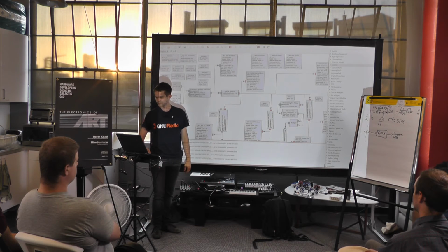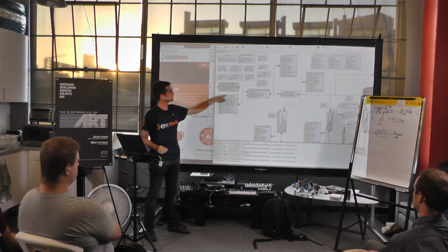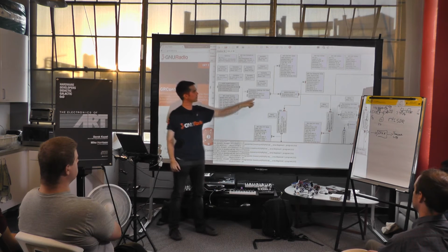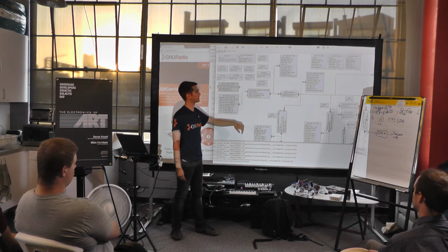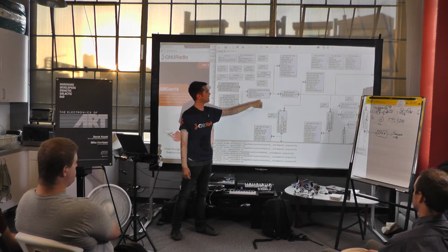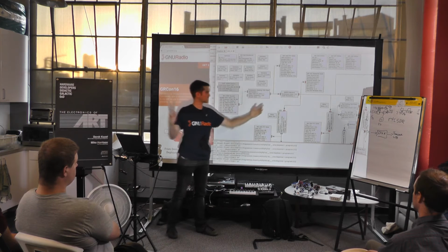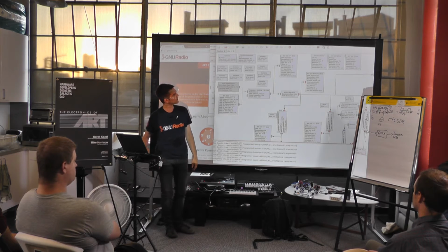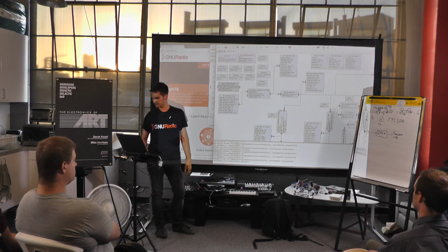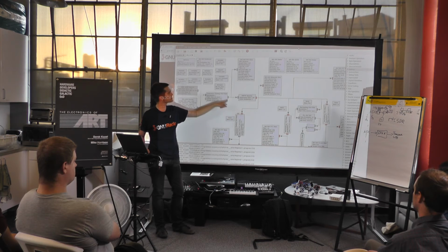And so if I drag this over a bit, you'll be able to see a bit better. So again, we have a radio source. We have a filter in the digital side. So again, if there's a powerful signal, this won't help me at all. But it's a signal. And then it's going into a wideband FM receiver. And it's demodulating the entire signal there. And then it breaks out into the different tabs that we saw there. So that path goes to RDS.